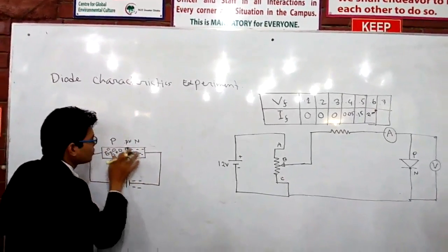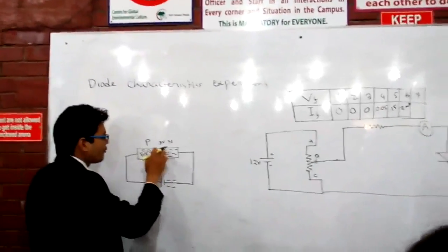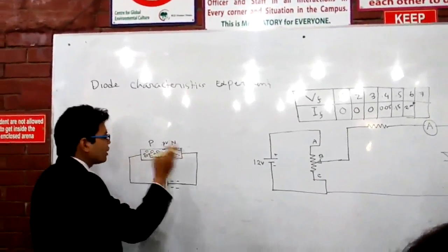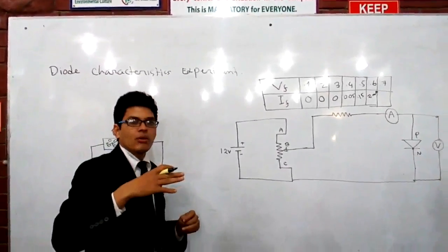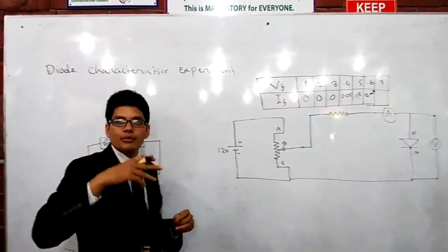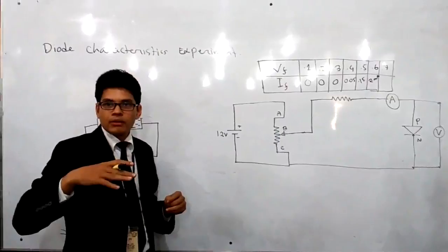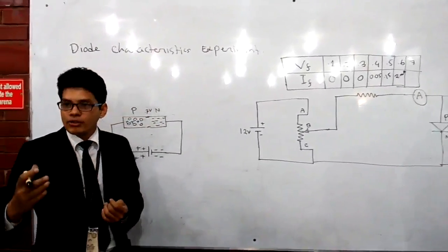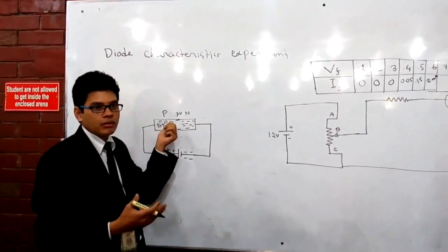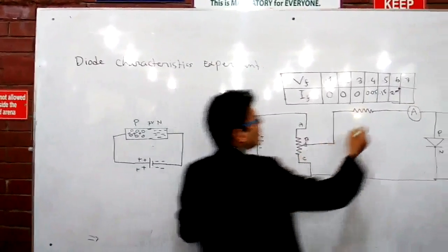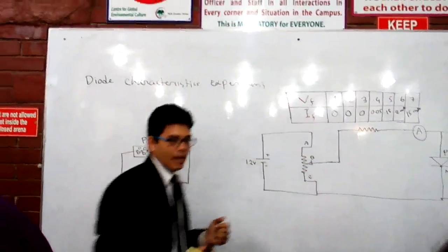And from 0.6 to 0.7, within this range, when it is 0.7, there will be no wall by now, right? The wall is broken completely. That means there is no resistance for now. So electrons will keep moving very fast. Once the electron is moving very fast, what will happen? That will make the current increase to high values, right? Because current is what? The flow of electrons. So once the electrons flow too much, the current will be more than maybe 15 milliampere, which is too high, right?